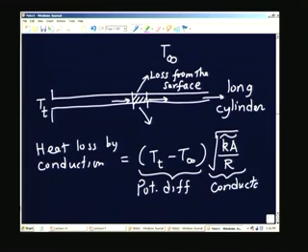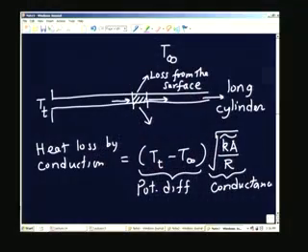So, product of two things. This Ka product represents the sum of K1 A1 plus K2 A2 for the two wires which make up the thermocouple pair. Okay. This expression comes basically from the solution to the heat transfer problem.